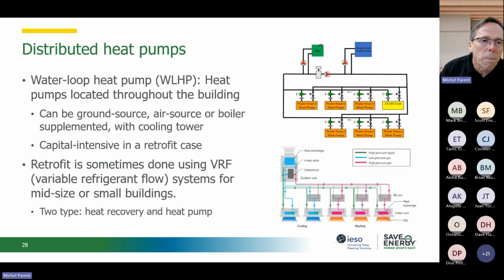So this heat pump has to be able to have really cold water in the winter, whereas your standard heat pump loop that's designed with a boiler does not have an extended range. It needs water in that loop that's probably no colder than about 64 to 68 degrees Fahrenheit in the winter. I'm sorry about the Celsius and Fahrenheit, so be careful.